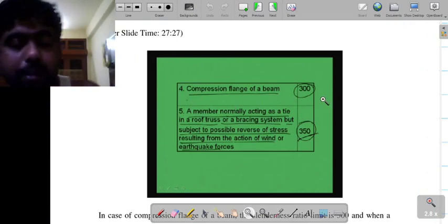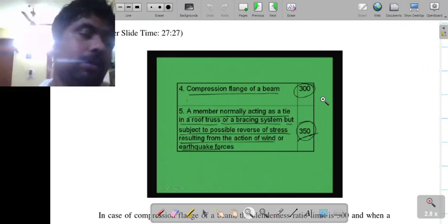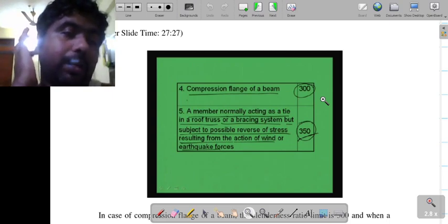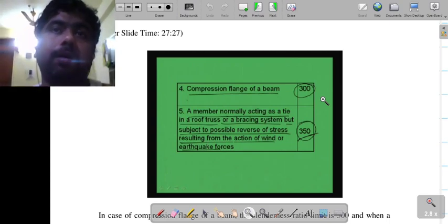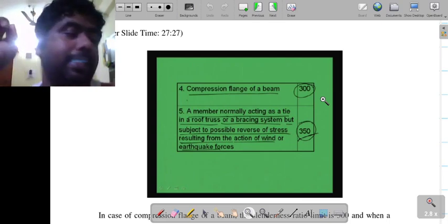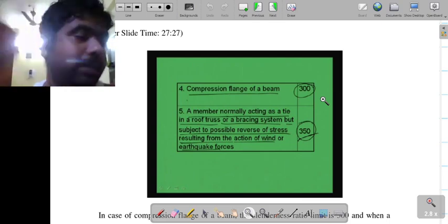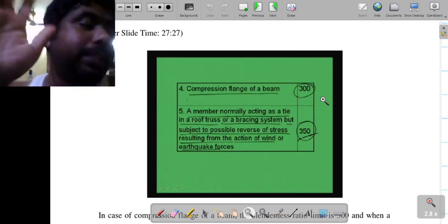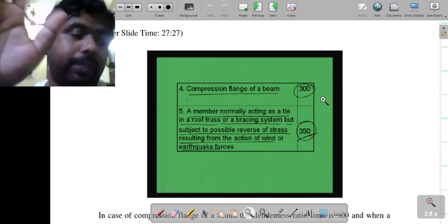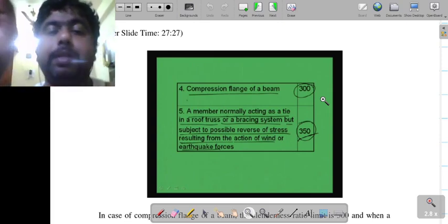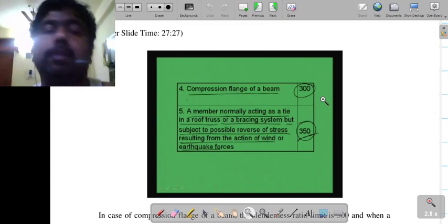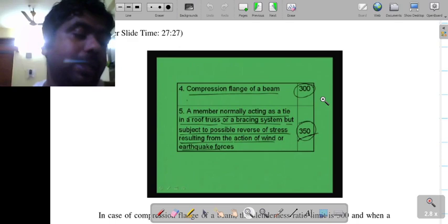Now, looking at a column with simple column information, we cannot say whether it is a simply supported column or some other type of support is given. So for that, there are simple guidelines. You may not find it in the code book, but in some books it is available. When we are using a web member, whether it is a riveted or bolted girder, whatsoever it is, simply take the effective length as 0.7 L. Say your support condition is not given to you, in that case you can take it like that.